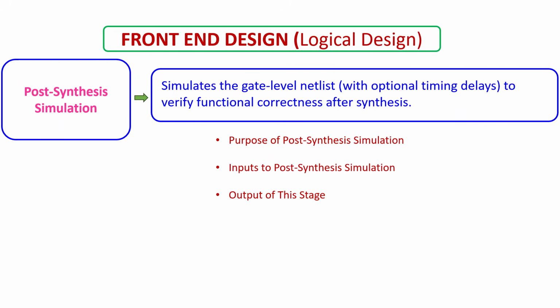The next and final stage is post-synthesis simulation. After synthesis, RTL becomes gates. But does it still behave correctly? This stage tells that. This stage verifies functionality after RTL is converted into a netlist. So what is the purpose of post-synthesis simulation? This post-synthesis simulation is a double check before moving to backend. It verifies functional correctness of the gate level netlist.